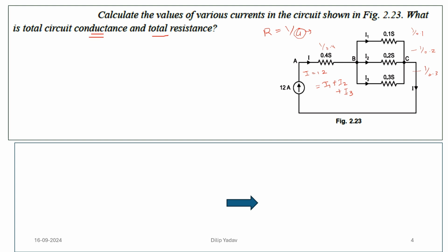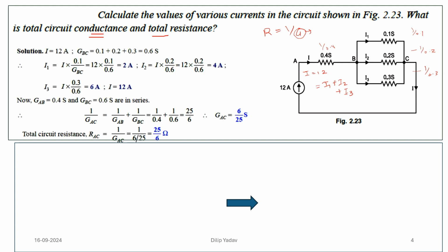So how are we going to approach this? This is the simple approach that we are going to follow. We have studied the voltage division and the current division rule. This is how we calculate in the current division rule. If I need to calculate the value of I1, then I calculate the total current that is flowing, multiplied by the resistance across which I have to calculate. For example, if I name it R1, it will be R1 divided by the total resistance. That was the equation.